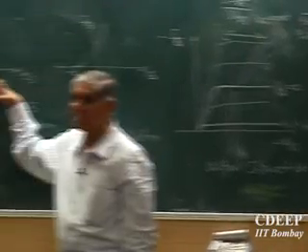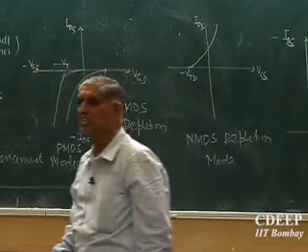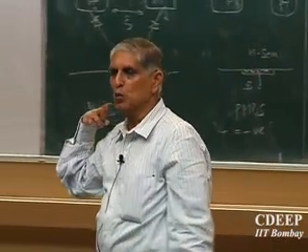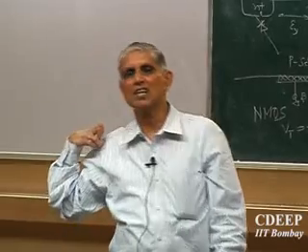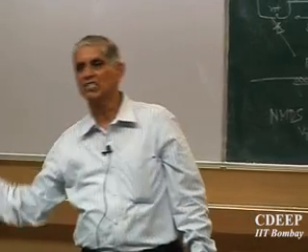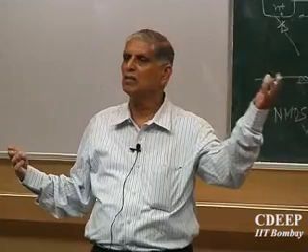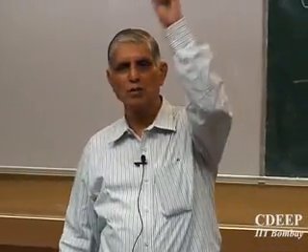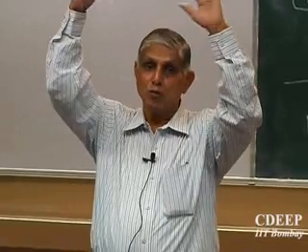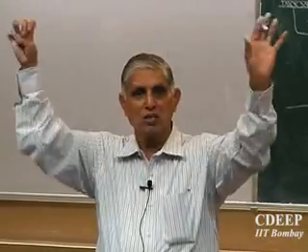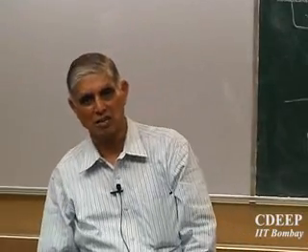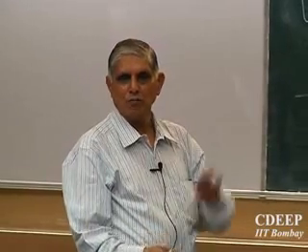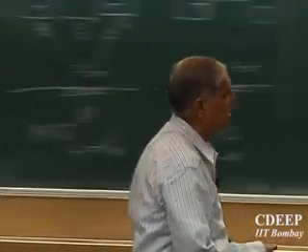Why did I show you all this? Because the characteristics of JFET, as the word goes, is essentially equivalent to depletion mode MOSFETs. And therefore I thought I'll show you that I can create JFET equivalent characteristics also in MOSFET by creating some kind of pre-doped channel there. Pre-doped means before I put bias, I have already created some N or P region there initially. So these four devices, now you got the point. These are four possible devices to show depletion transistors.